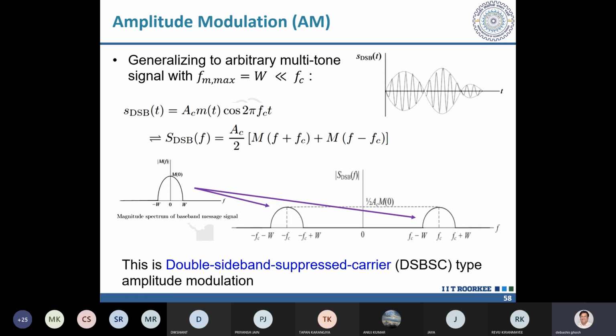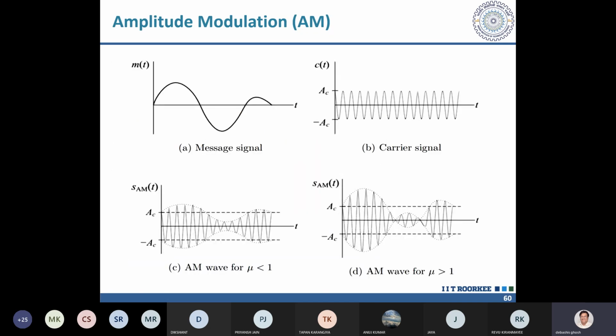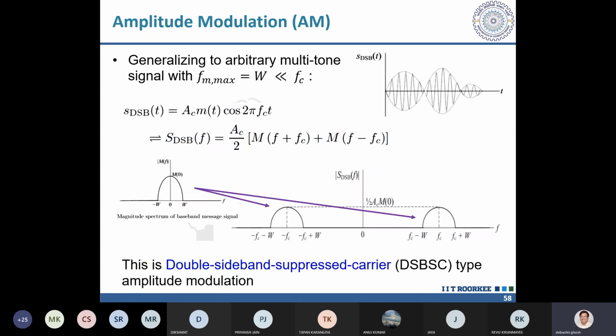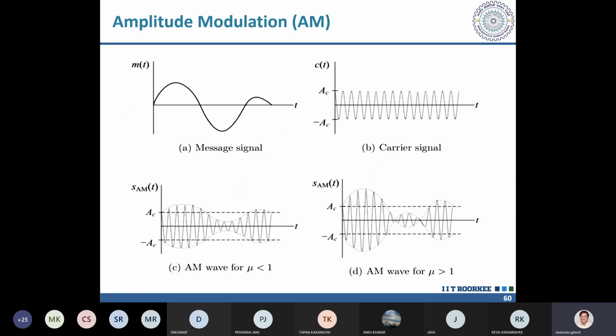the message signal. And now you see the difference. I have used the same message signal, and this is the carrier signal. When I do double sideband suppressed carrier, the signal would have looked like what I have shown here. This would have been the picture when I am multiplying them. When I am multiplying A with B, then I get the previous signal.